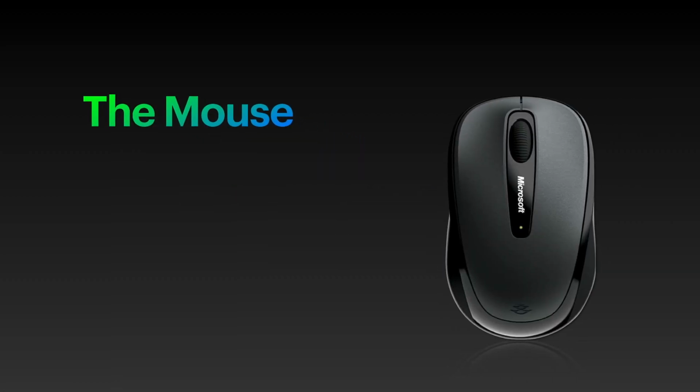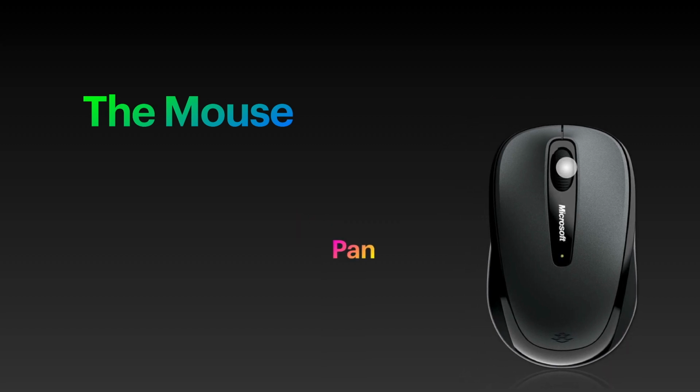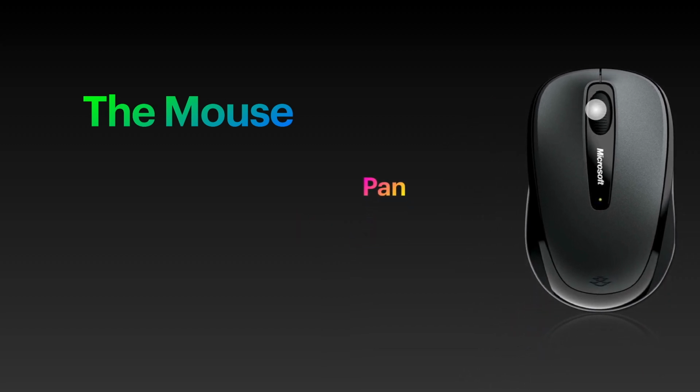For example, you would like to zoom out to see a large area of your drawing. Just scroll down the steering wheel of your mouse. If you would like to get a more detailed view of your drawing, scroll up to zoom in. And if you want to move the view of your drawing anywhere along the drawing area, click, hold, and drag your mouse to pan the drawing in your desired view.